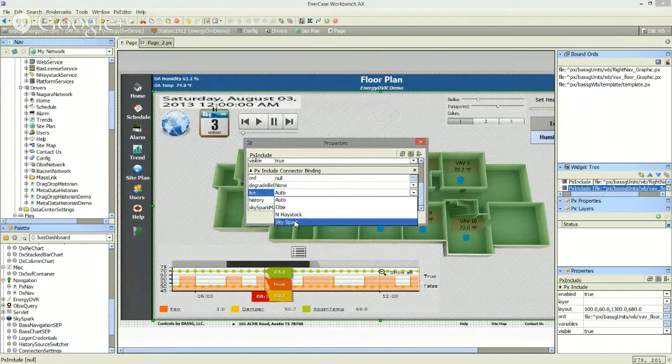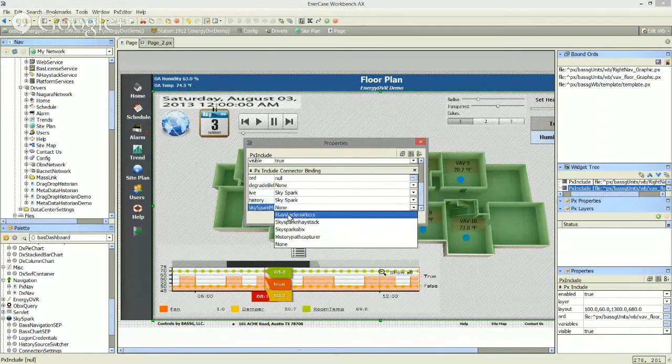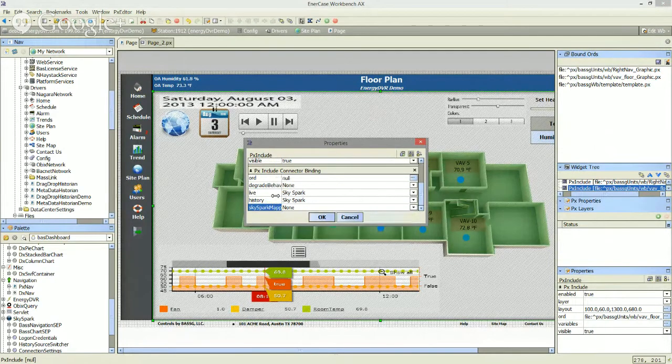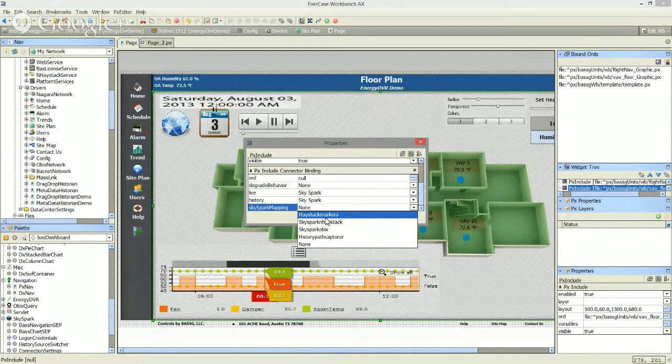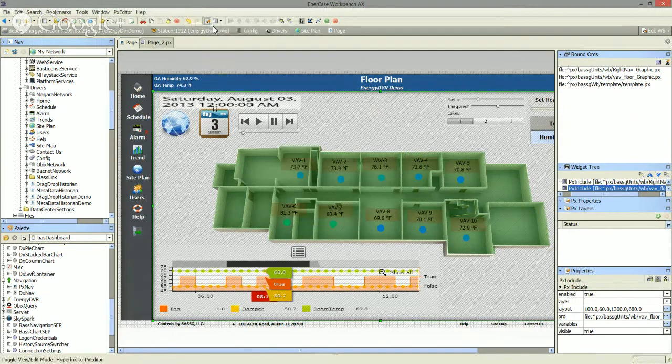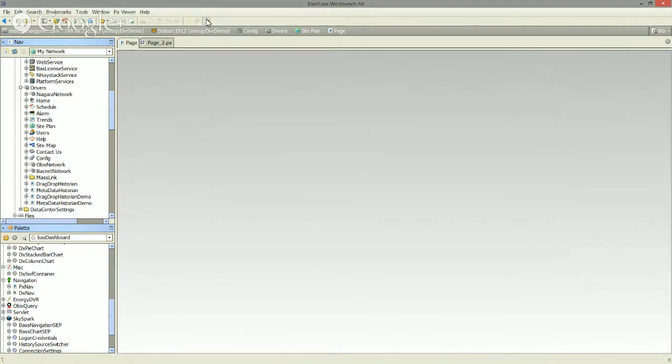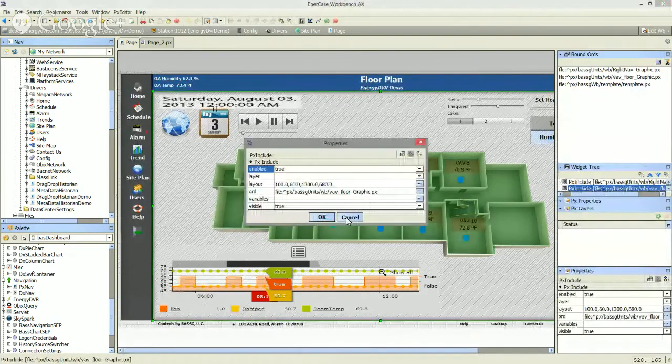And in here, you can change the live data and the historical data mapping. And you can change how the calls are made based on the mapping type. For the mapping type, you can have haystack markers. You can assign the markers, rec IDs underneath it, or you can automatically find it via nHaystack, AX slot path, and other things like SkySpark OBX or history path capture. So these are your options on how to override a mapping to grab the data from a different resource.